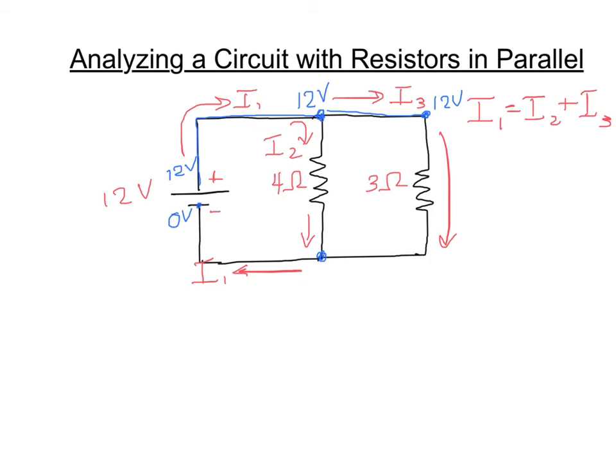Down here on the 0 volt side, if I think of this bottom terminal on the battery, that's at 0 volts. I trace this back to this junction here. I have 0 volts there. I have 0 volts there. Following the same logic, there's no resistors to diminish or change that amount of voltage. Why is that important? Because when I apply Ohm's law in this case, I'm going to apply it to try and solve for the amount of current in each branch. So I2 is going to be equal to the change in voltage across resistor 2 divided